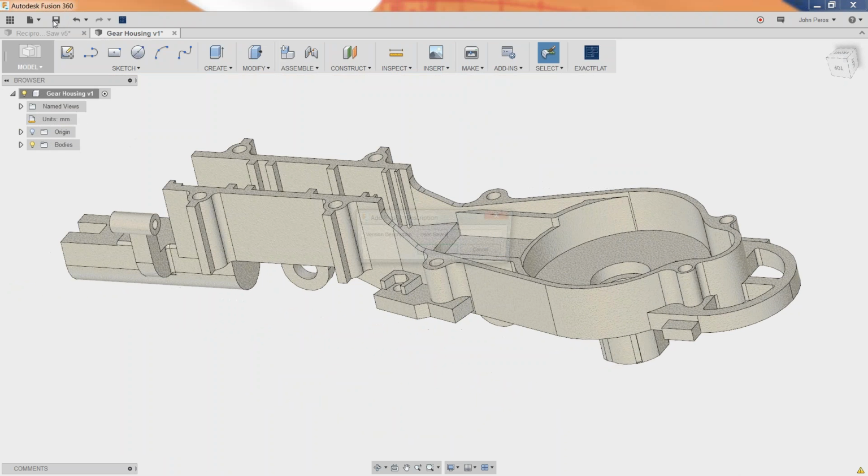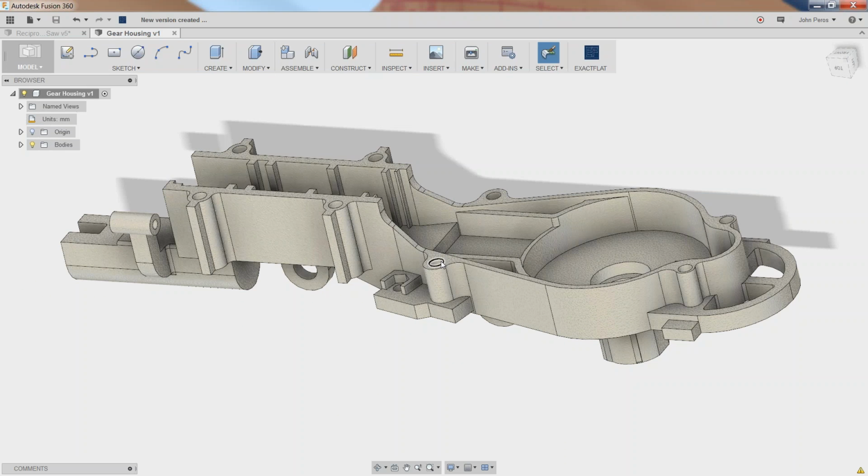So I'm going to save this thing. I like the way that worked. I can say made FEA edits. It's going to put a version up there and do all that fun stuff that it does. And when I swap back to the assembly, you guys are going to see something that you're definitely not used to. If I make this change, whether this was a change anyone knew I was making or not, anyone who was consuming this in a downstream assembly is automatically going to get my updates the next time they open their file.